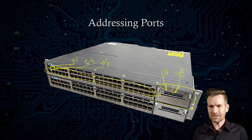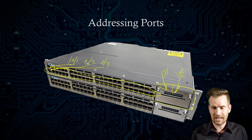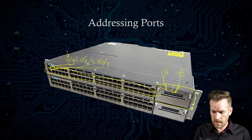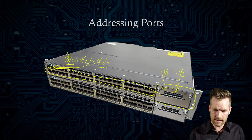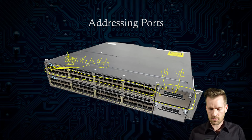And so we actually add another element to this also. There's actually a whole other slash in here. So this would be 001, 002, 003, and this is identifying the switch in there. So as we connect these together, then it'd be 101, the next one would be 201, 301. So this is identifying the equipment that it's connected into. This is identifying which of the components within the switch it's connected to, and then this is identifying the specific port.